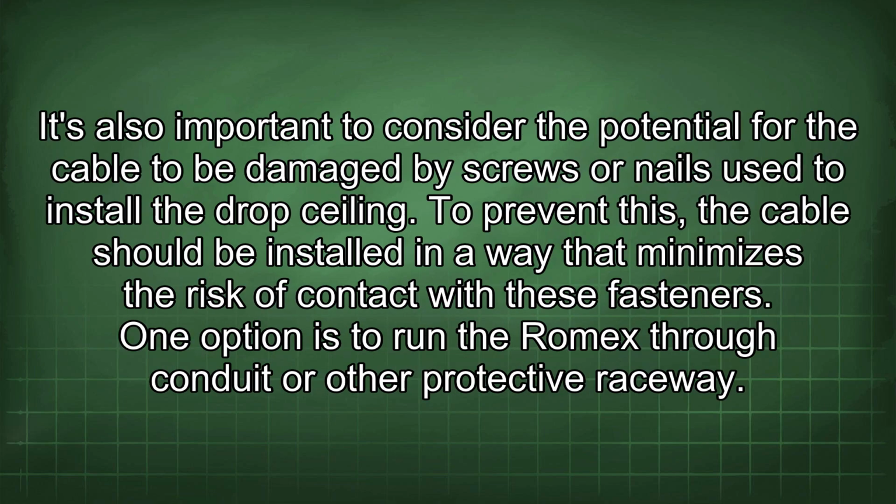It's also important to consider the potential for the cable to be damaged by screws or nails used to install the drop ceiling. To prevent this, the cable should be installed in a way that minimizes the risk of contact with these fasteners. One option is to run the Romex through conduit or other protective raceway.